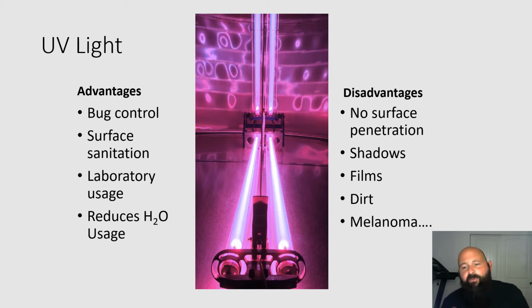If there's any shadow, I don't see how it's going to sanitize on the other side of that. If there's any biofilms or dirt or anything like that, you'll have some issues getting through it. And also having high-powered bulbs and things like that. Another thing is, I've gotten in a fight with one of these once where I was standing a little close to it, and I thought I was shielded, but I wasn't. It hit my eyes, and it burned my eyes pretty good. It didn't happen right away, but later in the evening, my eyes started to hurt really, really bad. So it doesn't seem like something that's injuring you initially, but can definitely have some impacts on people.